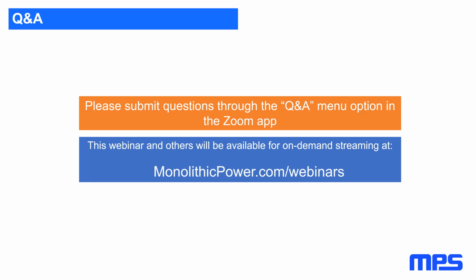You still have to consider the current through the low side FETs, and generally they're only on half the time on each phase. And then you may or may not need to consider the power that's dissipated in the clamp, which might be outside the IC. Usually it's a little easier because most of the time unipolar steppers are just driven in full step mode. So these low side switches aren't pulse width modulated. They're just turned on and off. So that simplifies things a bit.